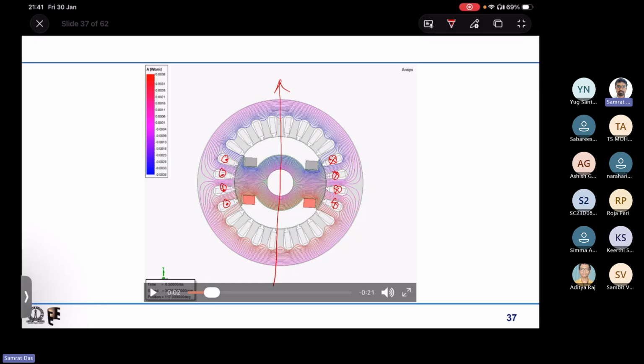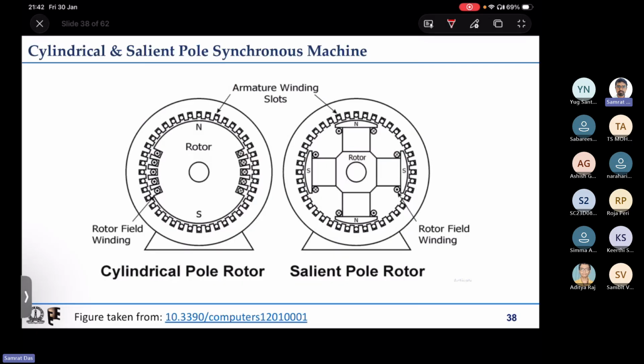So all three phase inductances are actually dependent on the rotor position if we have a salient pole synchronous machine. So the analysis that we do will be quite different for the two cases, the salient pole synchronous machine and the cylindrical rotor synchronous machine. And there will be additional torque for saliency also in the salient pole synchronous machine.